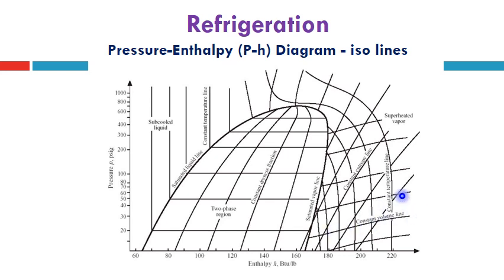However, the constant volume lines are shown in this direction, starting from the saturated vapor line. This area is mostly used during the compression stage to detect the starting point of the compression, either on the saturated vapor line, or moved to the right by some value for the superheating process, whether inside the compressor or outside, inside the liquid suction heat exchanger or outside.